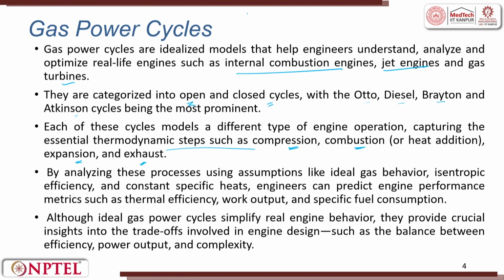4 steps, very easy. You have air, this air has to be compressed. You have air close to volume, it has to be expanded, right. Then when you compress and when do you switch to expansion? There has to be a process called combustion, blast, combustion. Once this combustion happens, the expansion happens, whatever is left out in the system has to be exhausted. 4 systems, 4 steps, right.